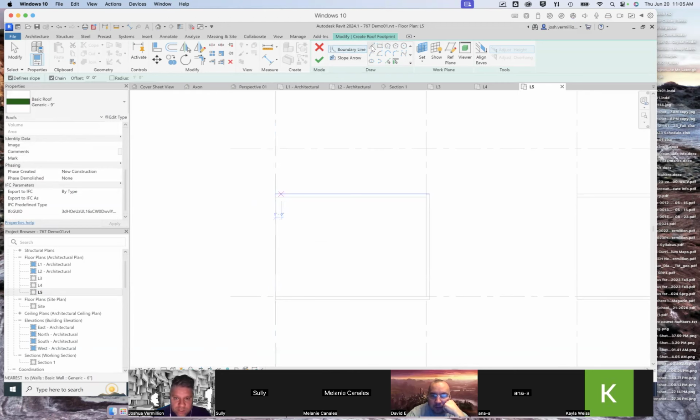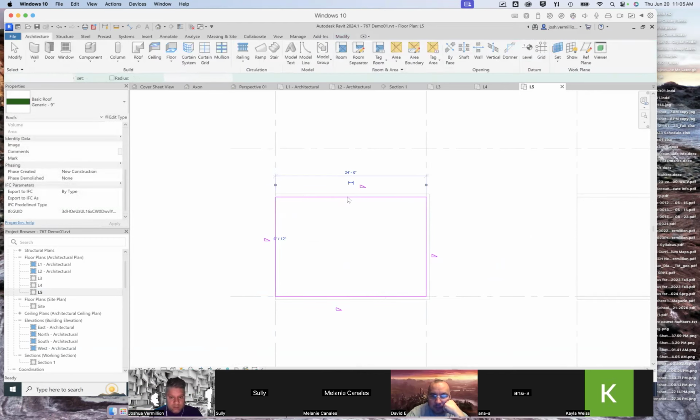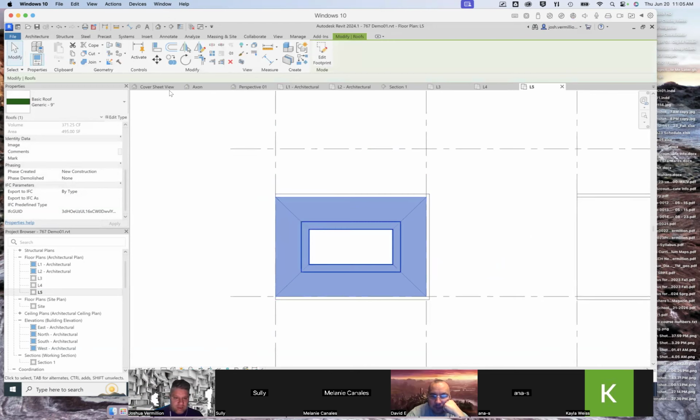You see there's multiple ways to draw this. I could draw a polyline, or I could click and then drag from one corner to the alternating corner to make a rectangle. There's different ways to draw in Revit, just like you would in Rhino. But I like to go around and be very particular sometimes, and anal retentive that way. And I'm going to hit the green check mark. Now let's see what god awful, terrible roof it gave me.